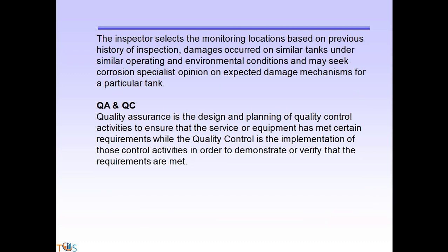The inspector selects the monitoring locations based on the history of inspection and damages that occurred on similar tanks under similar operating and environmental conditions, and may seek a corrosion specialist's opinion on the expected damage mechanism for a particular tank.